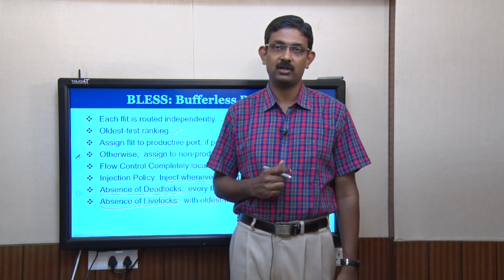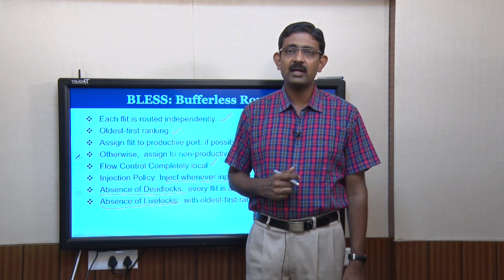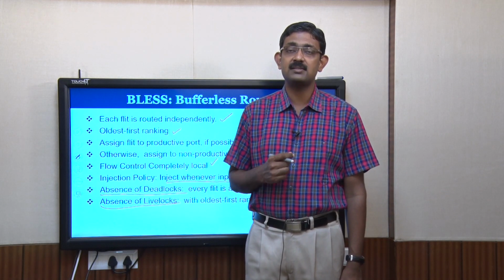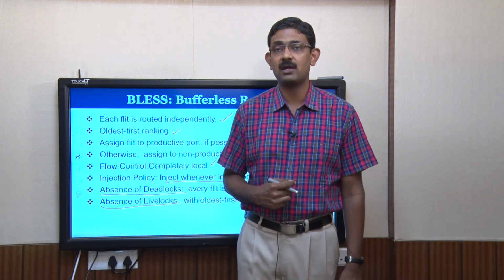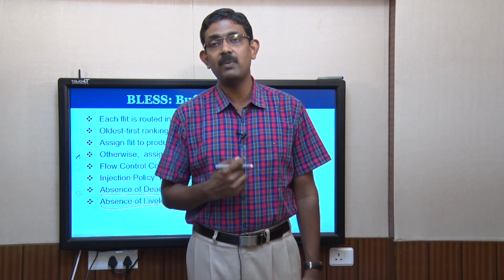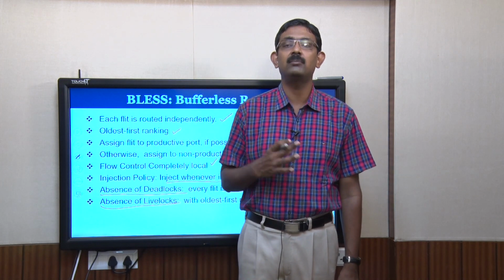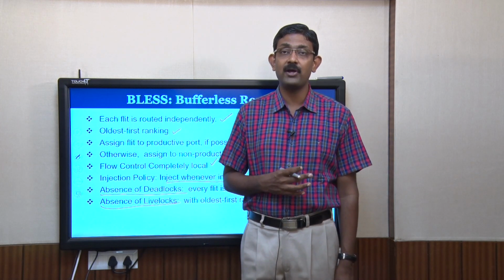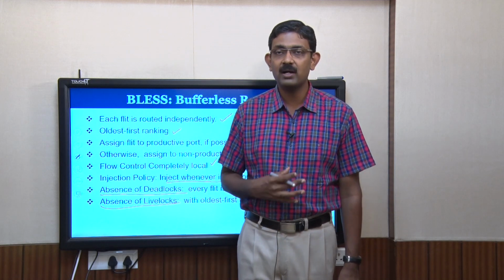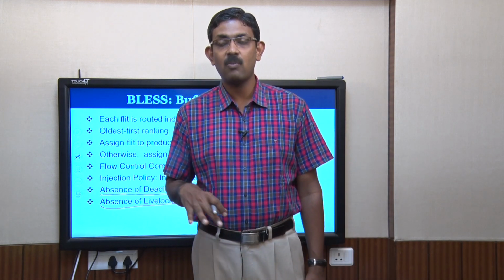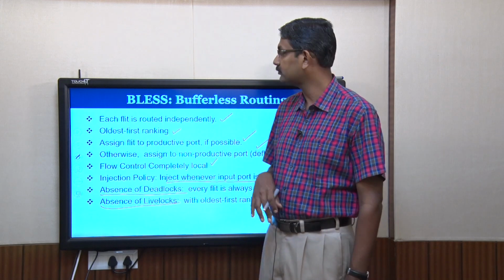So, there is no deadlock. And livelock is eliminated by virtue of oldest flit highest priority routing. The oldest flit will always get the productive port, and since everybody will become the oldest flit in the system at some point of time, once you become the oldest flit, there are no more deflections at all.